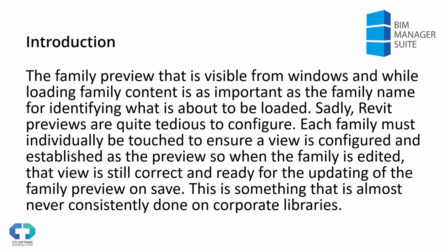The family preview, the little graphic that shows up on a family when you're clicking through Windows Explorer, if you have large icons, or while you're loading a family, to me is as important to identify what the family is and what it's going to do for me as the family name is. There are obviously other important properties as well, but that's visually some of the most important bits because it's my first impression of a piece of content and I get to understand what I can expect it to do.